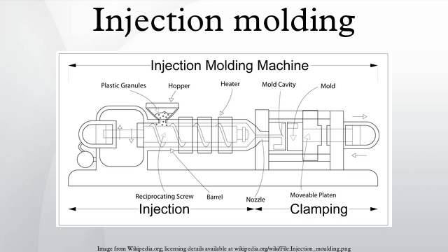The electrical discharge machining or spark erosion process has become widely used in mold making. As well as allowing the formation of shapes that are difficult to machine, the process allows pre-hardened molds to be shaped so that no heat treatment is required. Changes to a hardened mold by conventional drilling and milling normally require annealing to soften the mold, followed by heat treatment to harden it again.